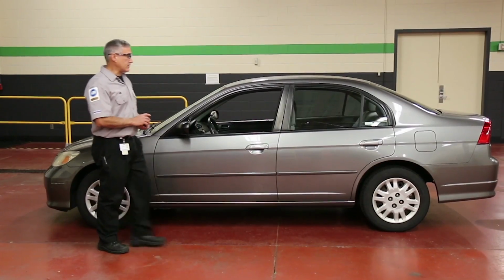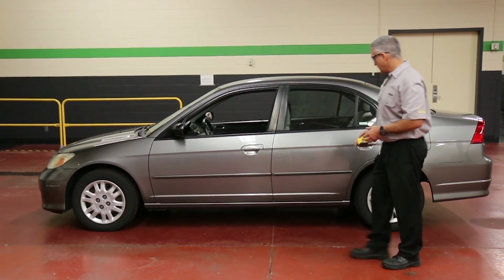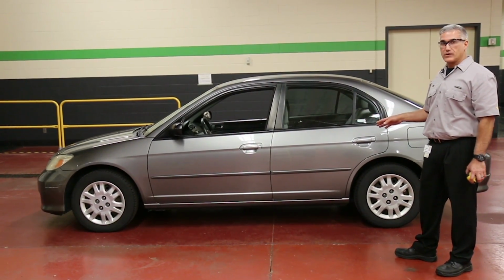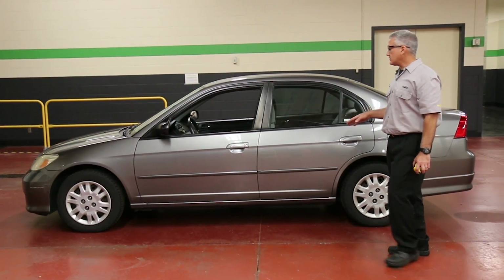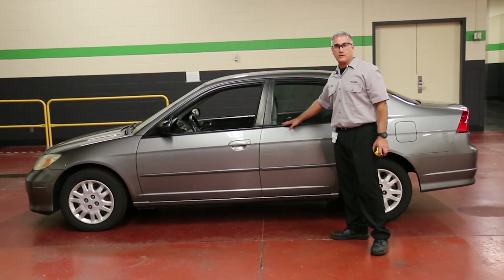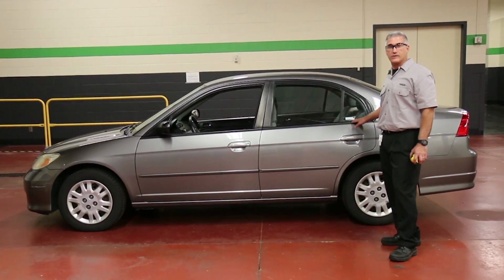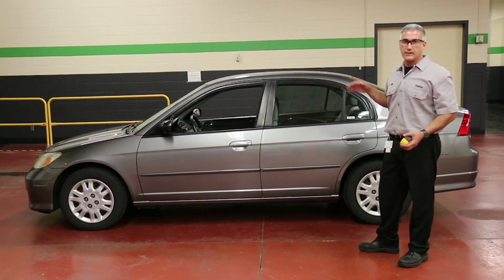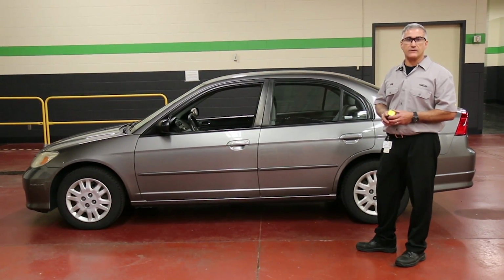Some other good indicators would be to look at the rocker panel of the vehicle. On most vehicles, the rocker panel is going to sit level, or it's going to be raked slightly high in the rear. You can also look at the windowsill molding. It should also be level or slightly high in the rear. And if it's a pickup truck, you can look at the bed of the truck. In the bed of the truck, same thing, it should be level or slightly high in the rear on most trucks.